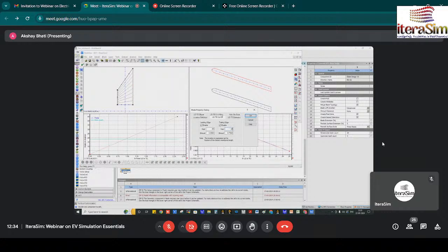Mostly in good practice you can take a 5% gap of the overall system dimension or overall fan dimension. And if you talk about the shroud, you give 5% on the shroud also, and 95% the total fan body in the requirement dimension.